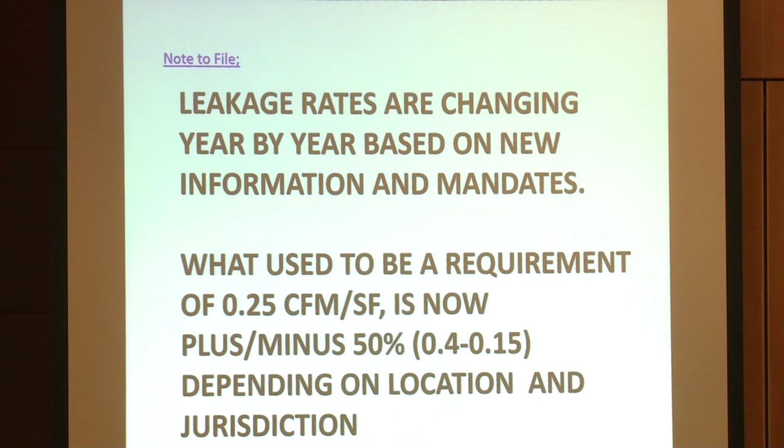If you look at ASHRAE Standard 90.1, you'll see that 90.1-2019 is on the verge of specifying it for commercial buildings. In the 2019 90.1, it's voluntary. But when they revise 90.1, which they do about every 3 to 5 years, I think you're going to see them try to bring in that pressurization.